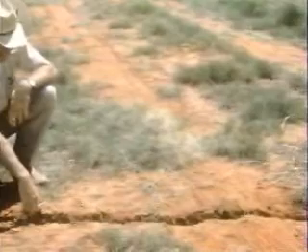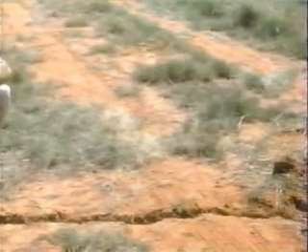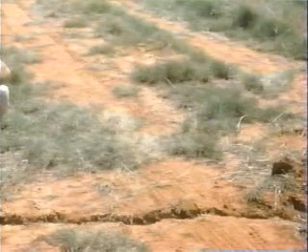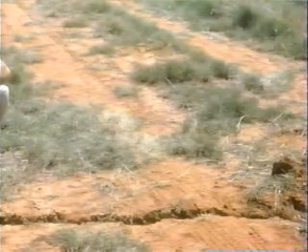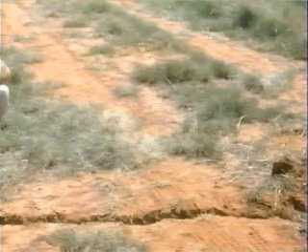Remember, these cracks appear in a direction roughly perpendicular to the length of the dam. For this reason, they're serious, because they can create a path for seepage right through the dam. Breaching of the dam could result.